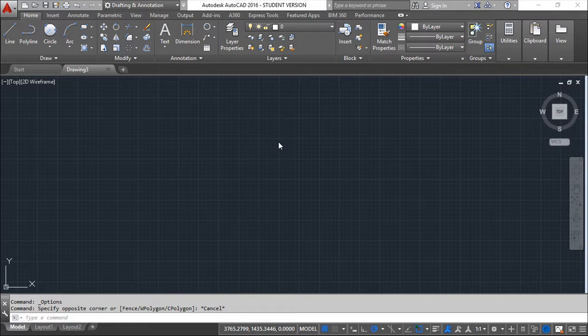This concept of the template is used to make the definition of a lot of things inside AutoCAD, things like layers, dimension styles, the configuration of the text, many things. You can even have already drawn entities inside your drawing that you use always or at least many times, and this way you avoid having always the same work every time you start a new drawing.